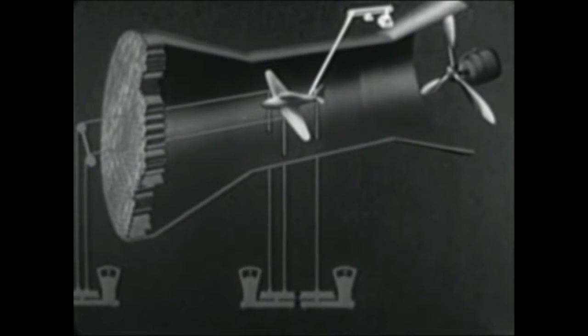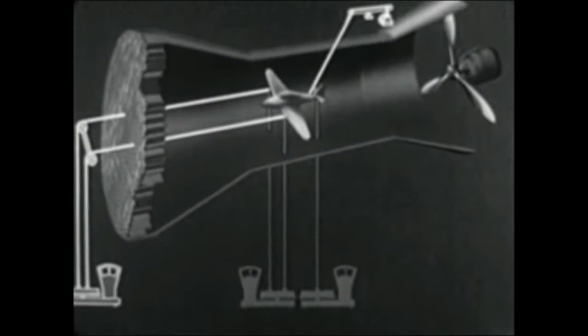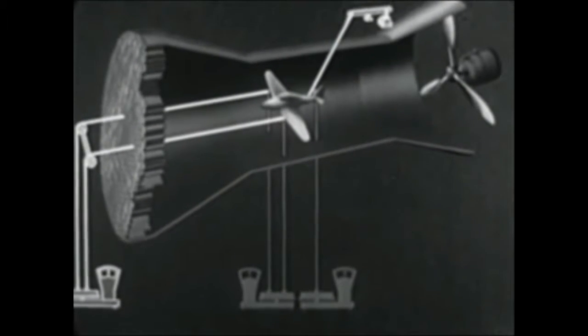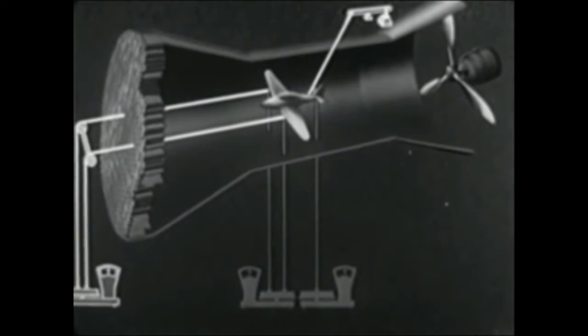One wire runs from the model through the top of the tunnel to a balance arm which is weighted so as to maintain tension and compensate for other forces. From the leading edge of each wing, a wire runs forward in the direction of flight over pulleys, and down to a bar on a platform type of scale.